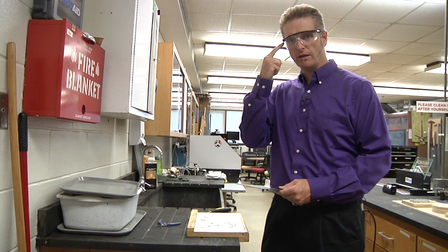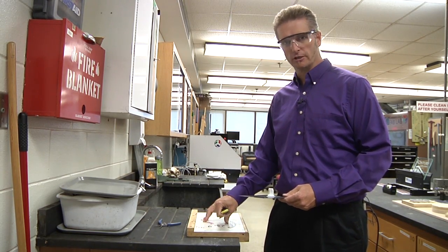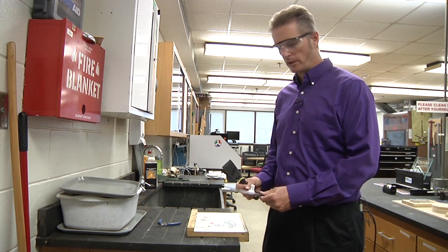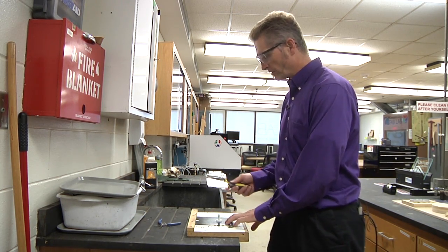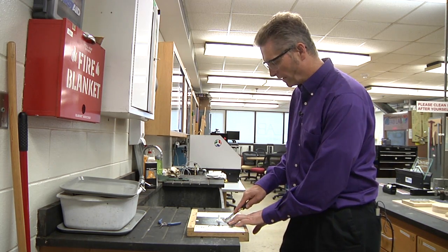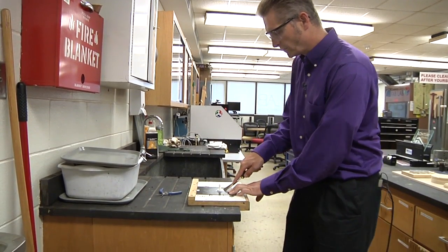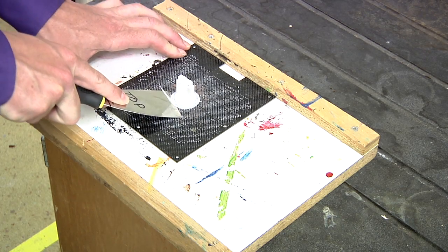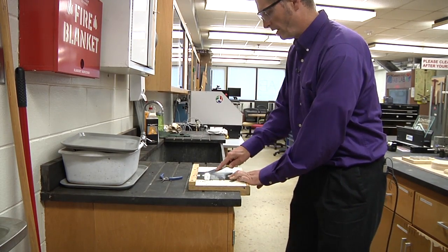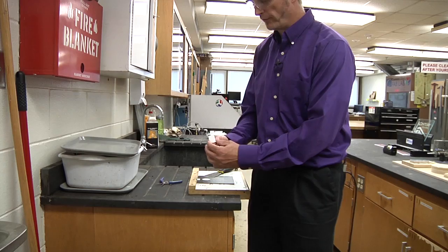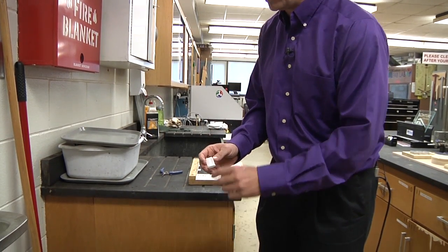Again, what we need is our safety glasses, our putty knife, and our bench hook. Now the way that we'll remove this part is that we'll place it flat on our bench hook here. We'll take our putty knife and work it right at the base of our part, and we'll push on it and work our way around. This sometimes takes a little bit of time, but you want to work that around, and eventually this will pop all the way off. And now we have our part removed off of the tray, and our raft has actually come off already. So we can throw this right into the garbage.